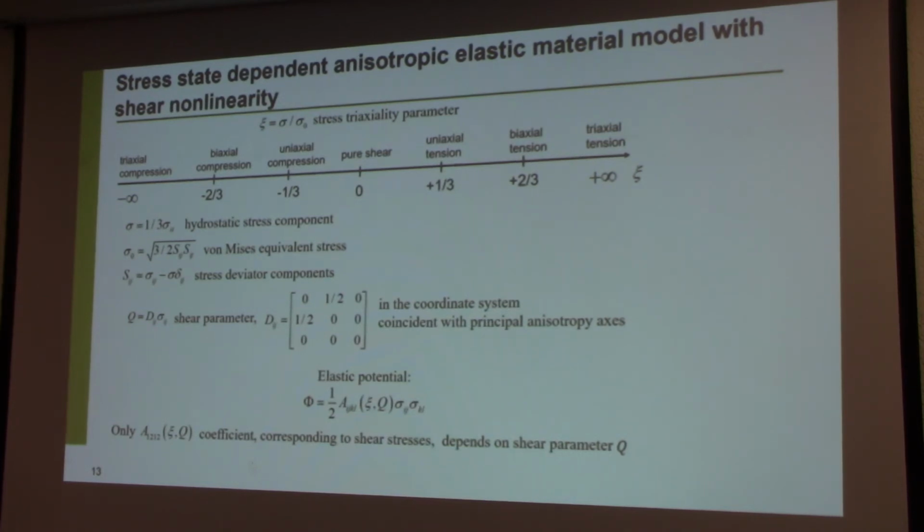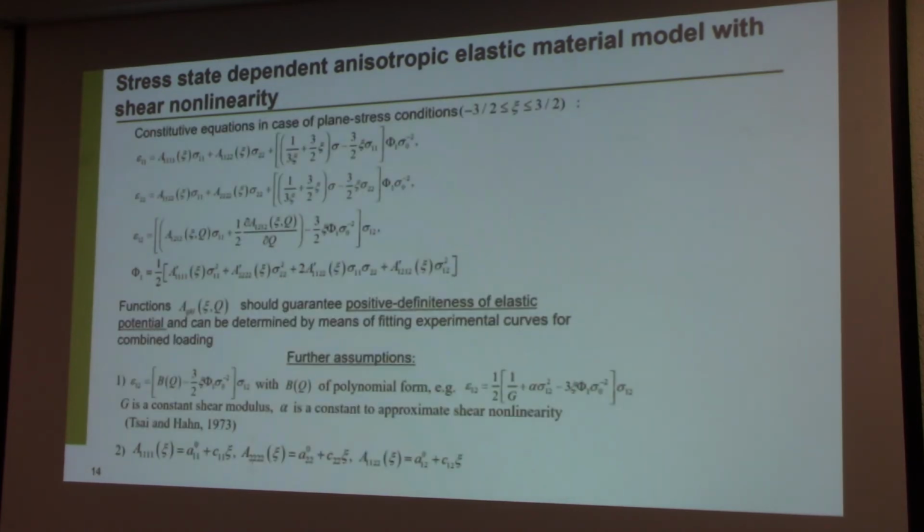We formulate elastic potential, which depends on classical view, in the way that the parameter has dependency on triaxiality parameter and also shear parameter. In case of this constitutive relation corresponding to that potential in the case of plane stress.